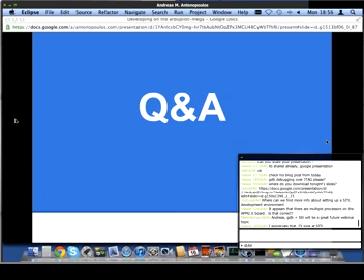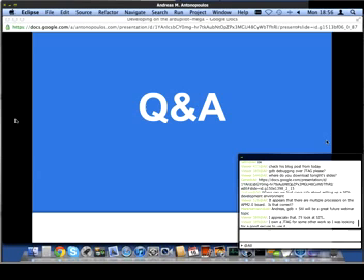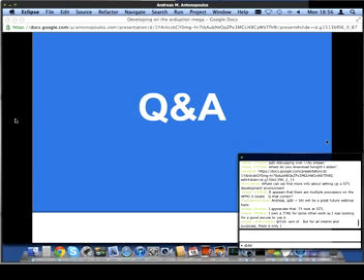It's only really used for very low-level debugging stuff. I've used JTAG to do a bit of low-level coding on the 3DR radios, for example, but I've never needed to use JTAG to talk to my APM1 or APM2. But I know that some of the people programming the little servo controller CPU, the 32U, use JTAG to talk to it. So basically JTAG is for the hardware that you can't simulate in software, because if you can, you do.